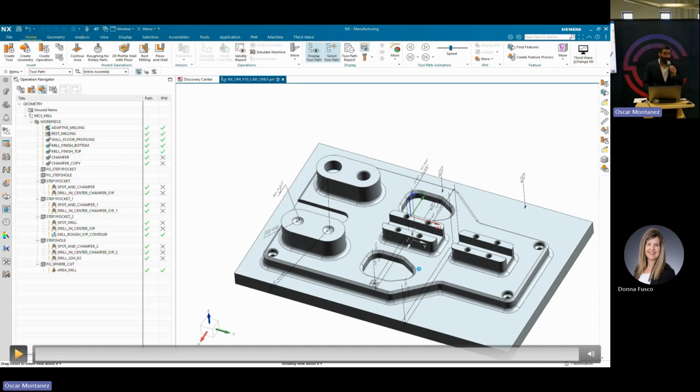But right now, if I have a surface finish call out on one of them for an RA value of 3.2 and the other one at 25, it's going to use the same operation set. It doesn't know right now how to distinguish between the two because we haven't set up the rule yet for what to do with the PMI. It's reading the PMI, but it doesn't know what to do with it yet.